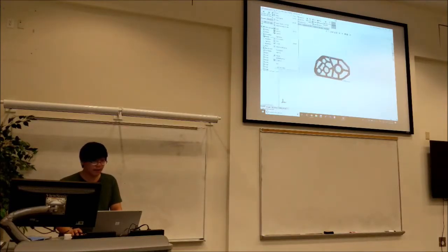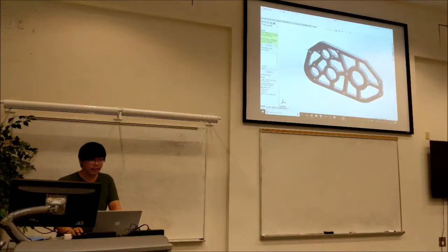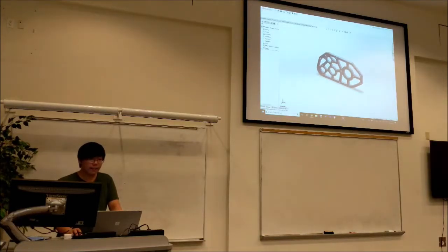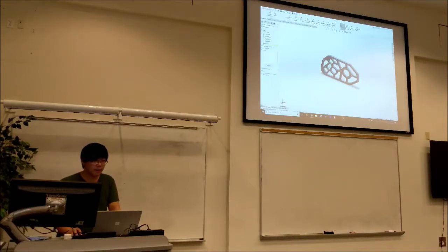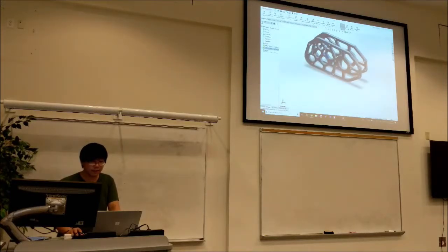So now we can go to an assembly. And at this point, your gearbox comes together really quickly because this plate is the most time-consuming part of designing a gearbox. Otherwise, it's just a bunch of mates, putting your motors together, putting the gears in, the bearings. So it's not that time-consuming afterwards. This plate is basically all you have to design, besides standoffs, which is just a cylinder you extrude.